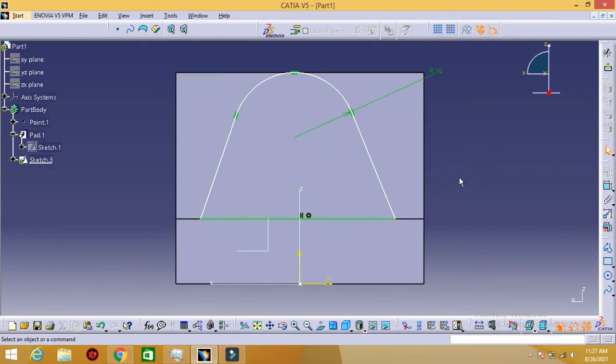For doing that, what is the process? Same program. You click on this point. When you bring your mouse to this point and click it and take it outside, see only the color of the point has changed. Now it is selected. Now press Ctrl and click this line. On this sketch, only this green line is selected.